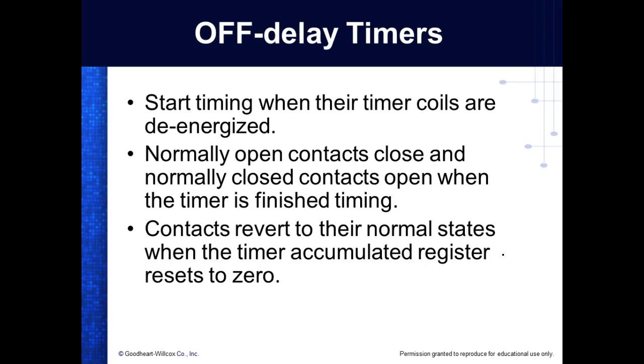Yeah. So normally sensors give us back a voltage when they're true, and no voltage or 0 volts when they're false. But that's only true if they have two outputs. We do have sensors out there that we call 4-wire sensors that provide a normally open and a normally closed contact. So that's where you've got to be kind of careful depending on which one of those contacts you use on those sensors. Does that make sense?